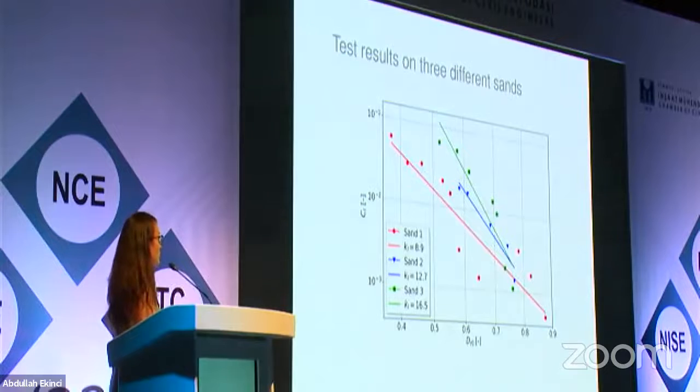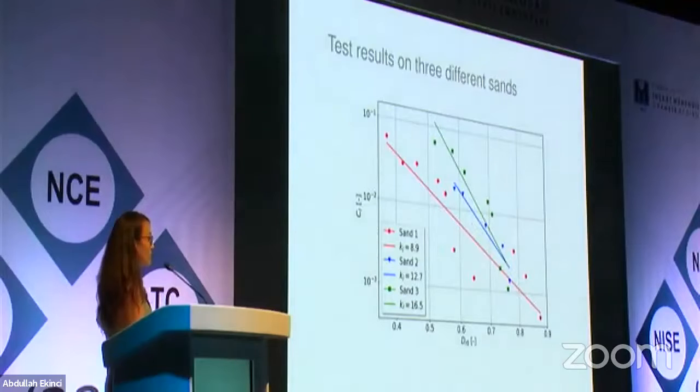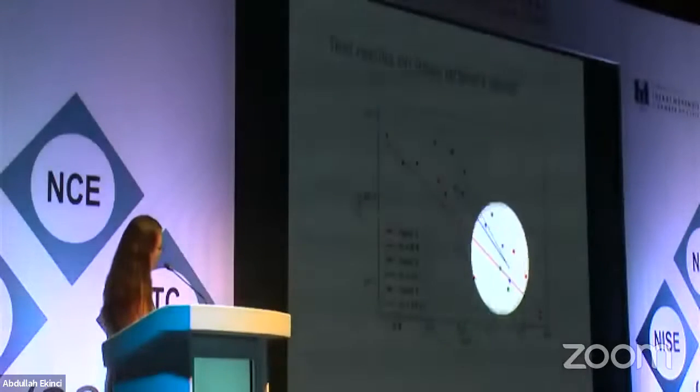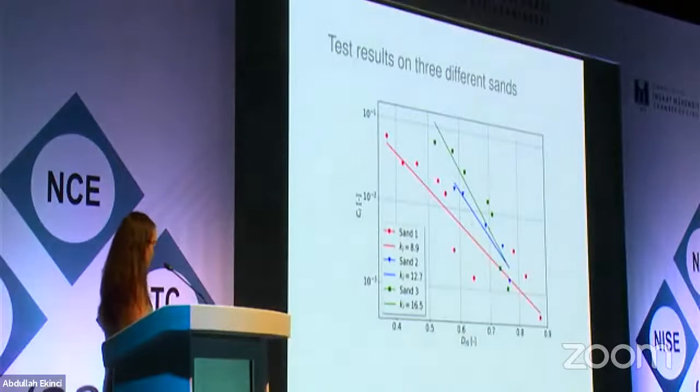I still want to point out that these are still the loosest possible states according to this deposition method. But when determining the initial relative density based on the conventional limits of the density, they fall into this medium dense range. There is also obviously some scatter in the results. We are working on clarifying this scatter. Most likely, the scatter comes from the saturation.